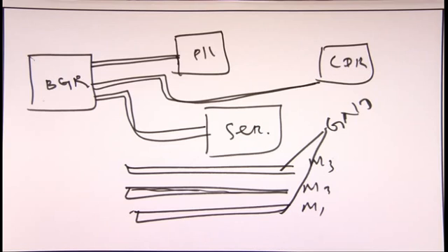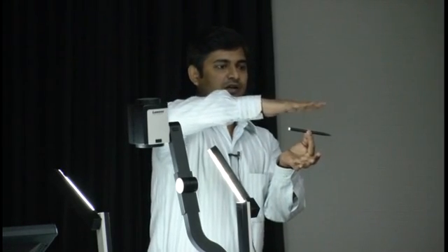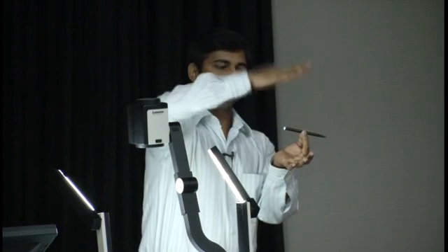Side by side you can also put shielding. Suppose this is metal 2, this is metal 1, this is metal 3. Here we can put metal 2, here we can put metal 2. Then it is shielded from everywhere. No noise will come from top, bottom, or side also. Okay, that is the main 3D shielding.